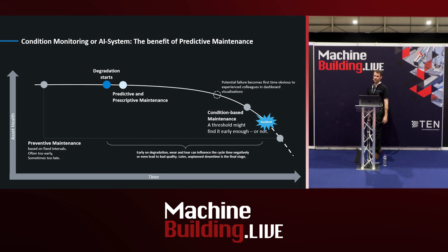And during this time when the degradation starts and when we can actually detect it with predictive maintenance, this is where we start to find the impact on OEE and the performance of the machine. This will even start to impact the cycle rate, the time. Let's take a pneumatic cylinder. If it's leaking, its positioning time from point A to point B starts to get longer and longer and longer, impacting the output of said machine. Okay? So all of this is impacting the overall equipment effectiveness.